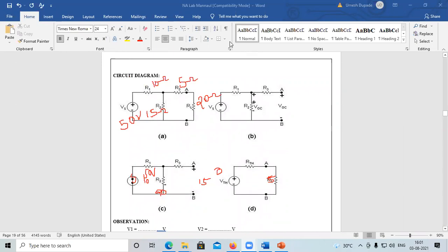So see. Now, do you know the first step when considering a circuit? The first step is to remove the load resistance RL. When removing the resistance RL, it will look like this. Again here 50 volt, then 10 ohm, then 15 ohm, then here 5 ohm, and here it is open circuit voltage VOC, or it may be VTH. We represent between terminals A and B the voltage VTH or VOC.